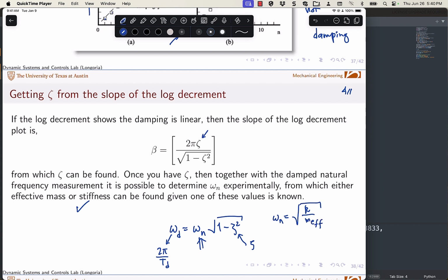So you can see what that effective mass is. Does it follow that formula from Den Hartog? Part of it is the end mass. Maybe the other part is some fraction of the beam mass. And does it follow that formula? Remember, this is all about how well you can make measurements, how close you can come to that theoretical value. Always remember, if you've made all your measurements well, then the experimental value is what you trust, right? And you want to see how good that theory is, because if that theory gives you some confidence, you can use it in future analysis. It's harder to run experiments, but this could give you some confidence in using a result like that.